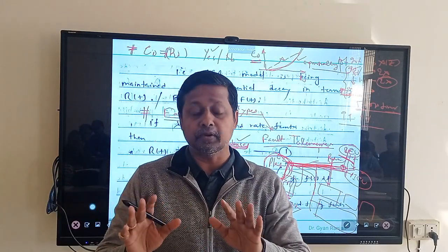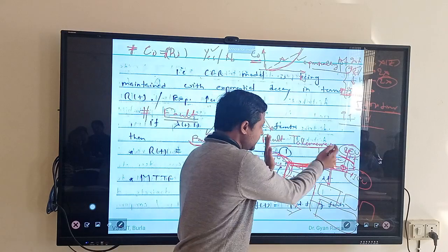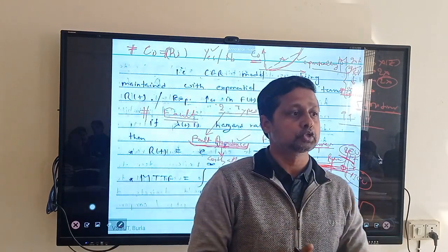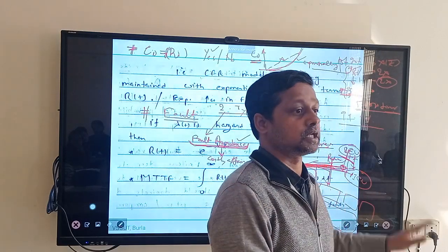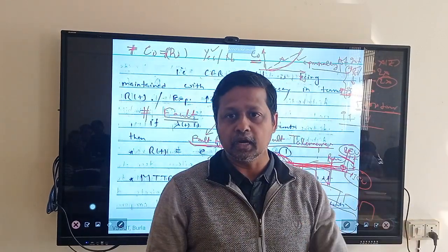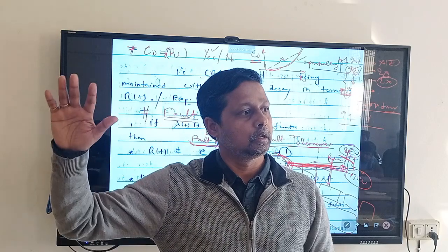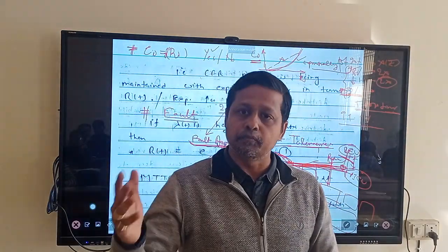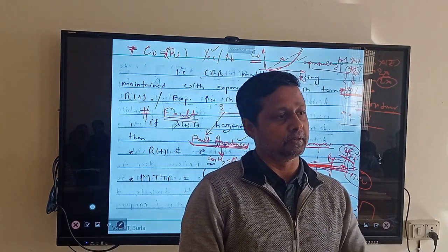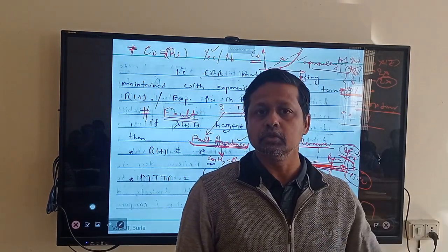So in that case, if I can plan my P&I diagram in such a way that it requires the least number of components to be involved for the successful execution, then on one hand I am reducing the proportional amount of failure rate. Number one. Okay, obviously a lesser number of components will definitely impact the cost, your cost will reduce.